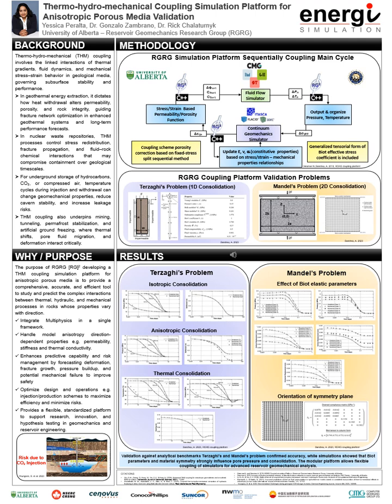In summary, these three benchmark cases, isotropic, anisotropic, and thermal consolidation, demonstrated that our simulation platform can reliably capture the coupled hydromechanical and thermo-hydromechanical behavior of porous media. Now let's talk about the second benchmark problem, which is the traditional Mandel's problem. It assumes normally isotropic material properties.